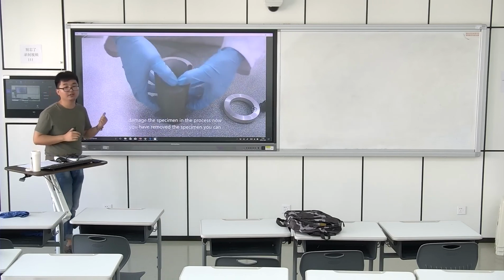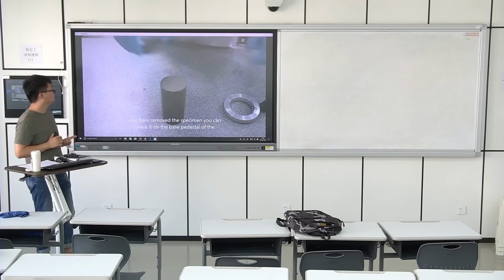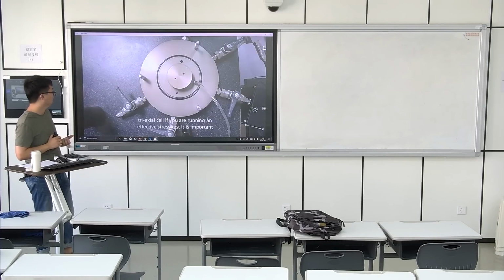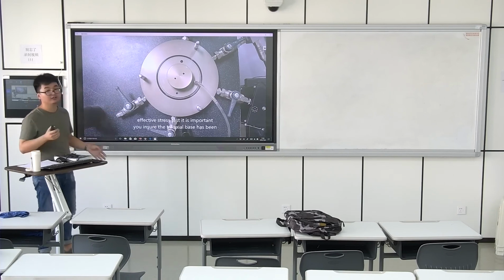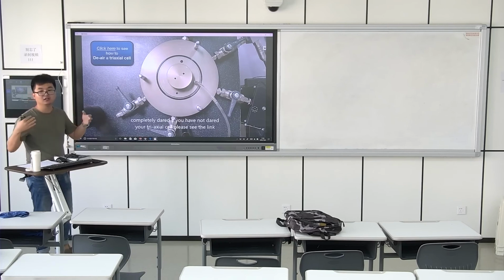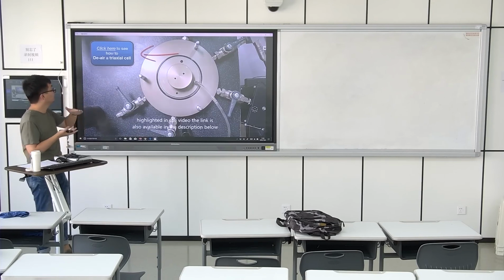Completed. Now you have removed the specimen, you can place it on the base pedestal of the triaxial cell. If you are running an effective stress test, it is important you ensure the triaxial base has been completely de-aired. If you have not de-aired your triaxial cell, please see the link highlighted in the video. The link is also available in the description below.